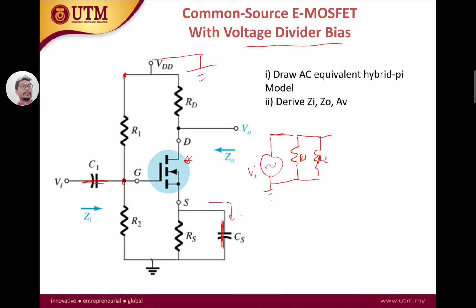Okay. And then we draw our small signal equivalent circuit. So here is our Vgs, it looks something like this. Okay, and here is our gm Vgs. Here is our source, here is our drain, here is our gate. So our RS is gone, but we have RD connected to the ground. So RD is connecting drain to the ground. And then on V out we don't have an RL. Okay, there is no more resistor.